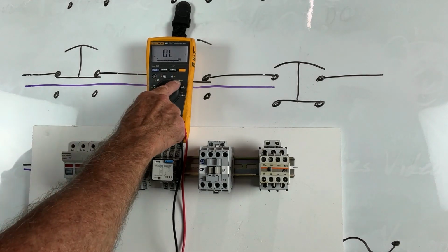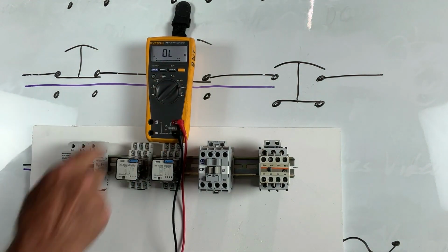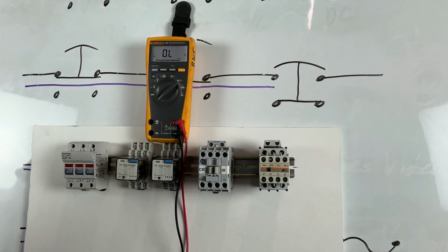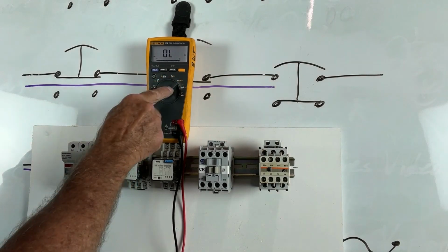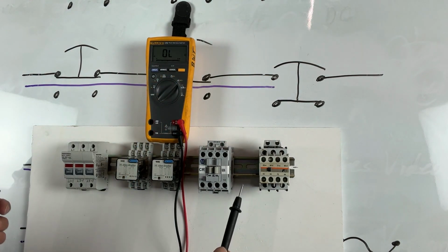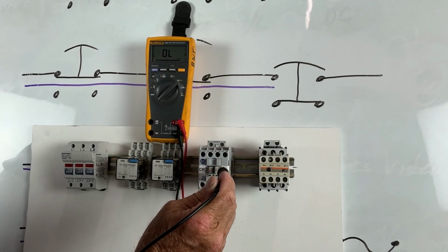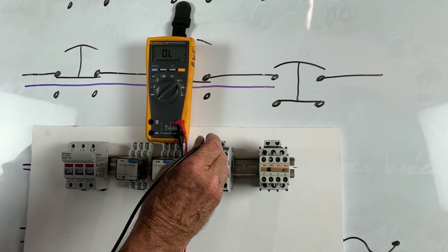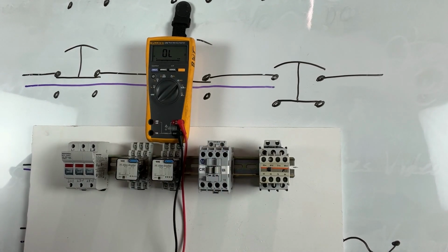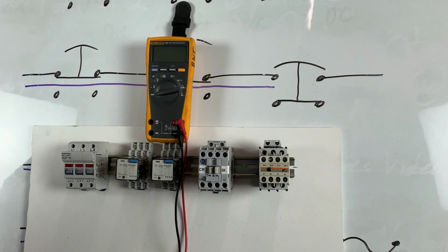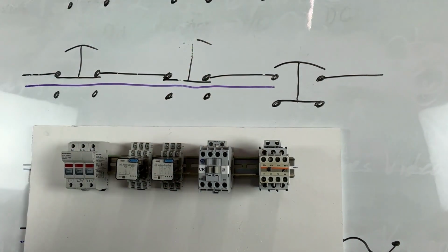So, you know, you have to really be watching your meter when you're doing this, and if you're having issues even after you've checked it out for continuity. So just keep that in mind when you are doing the beeper, that you can have a certain resistance, which, if you remember, was greater than the resistance of this coil. And that coil is a load. But this is a tremendous tool, and a skill to have is to know how to use your multimeter for resistance measuring and for your continuity.